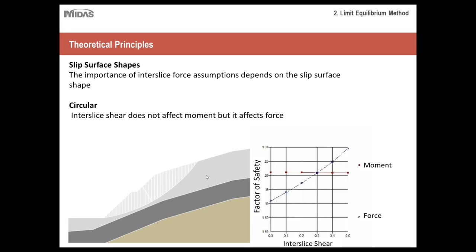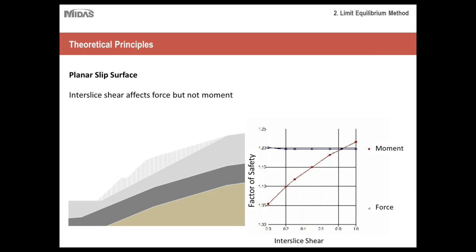Depending on the type of forces you see acting on your slope, a circular arc failure surface may or may not be ideal for you. If you're expecting little to no rotational force acting on your slope, then a circular failure surface might be your best bet, because you'd only need to account for the shear force or the lateral force. Whereas if you were expecting a significant amount of rotational force, then this circular arc failure surface would not be as efficient, because you wouldn't be able to account for it. So let's take a look at another type of shape here.